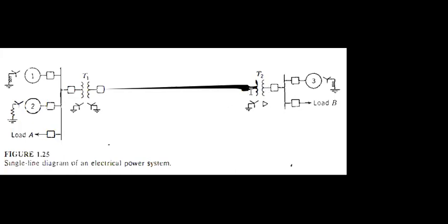And on the right side, you have another transformer with Y delta configuration. As you know, the transformer might have YY configuration like T1, or Y delta configuration like T2. The phase group or vector group was discussed last semester in phasor analysis, like YD1, YD11, DY1, DY11, YY6, DD6 and so on.